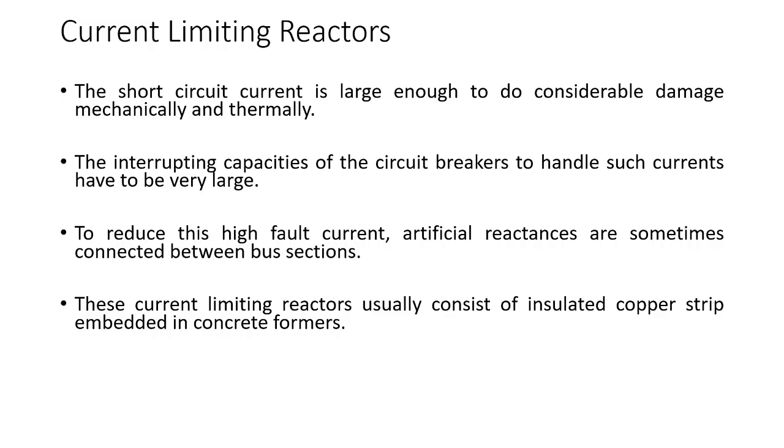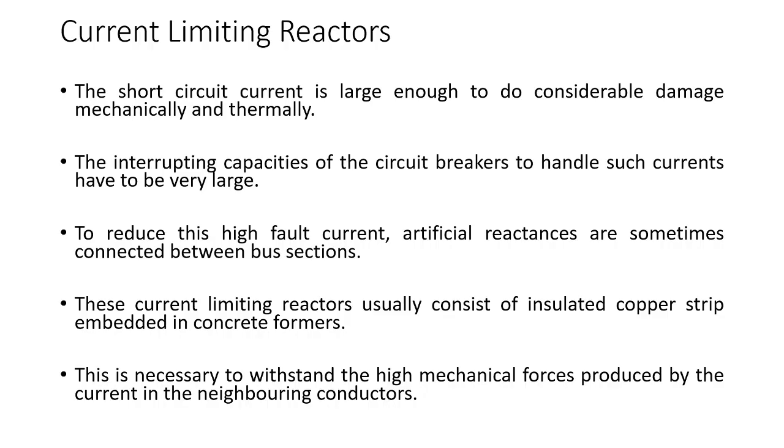These current limiting reactors usually consist of insulated copper strip embedded in concrete formers. This is necessary to withstand the high mechanical forces, that is, the mechanical support given by the concrete formers is necessary to withstand the high mechanical forces produced by the current in the neighboring conductors.